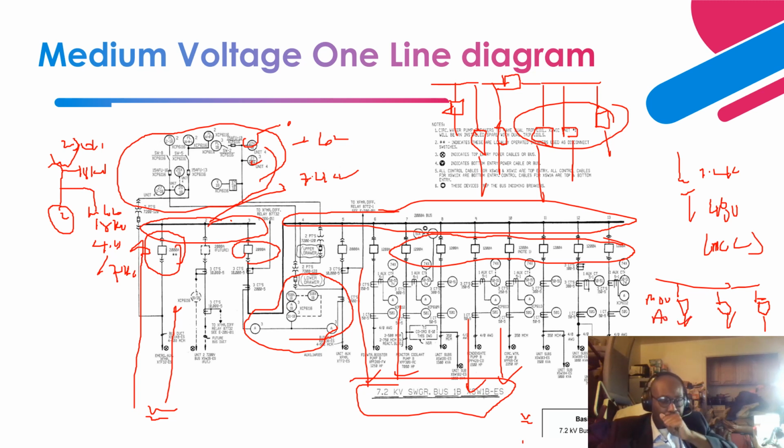Okay, so these are all the relays that are used to protect this feeder, right? A lot of the relays you see over here are 50 phase instantaneous and 51 phase time over current relays, right? Then you can have a zero sequence relay that is detecting ground faults, 50N and 51N, right? So you should be able to detect phase faults, that is phase instantaneous, phase time over current.